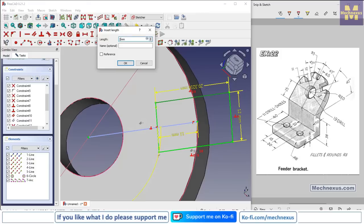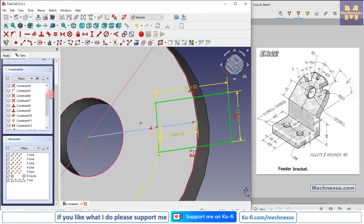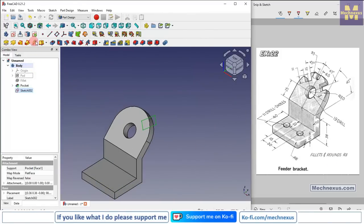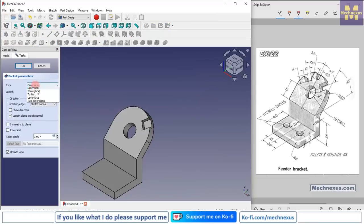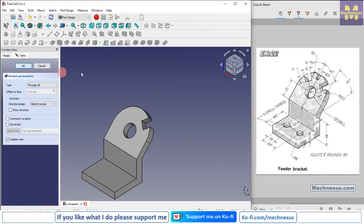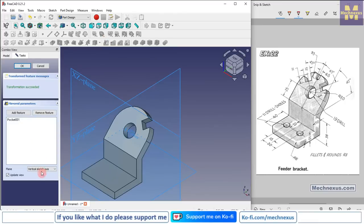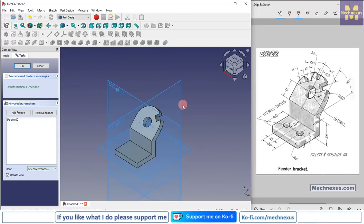Let's give the 20, and now we will close it and we will click on extrude cut and set it through all, say OK, select pocket, use the mirror and select reference, mirror on other side.